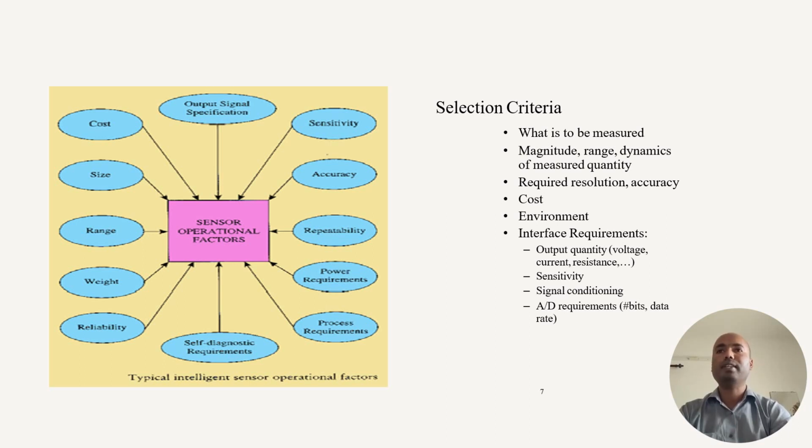So how sensibly it measures the measurements. The next is the accuracy of the particular component. Even if it is on temperature, if 0.1 degree Celsius changes in the temperature, it needs to measure the accurate level of the temperatures. Like if it is an automatic climate control, each and every degree Celsius it needs to measure. It needs high accuracy resolutions.